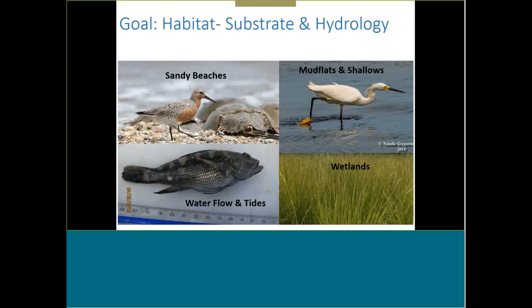And if you're coming at it from a habitat standpoint, looking at wetlands, it's important, as Chris mentioned, to make sure that you're selecting your plants based on what conditions are already there. If you're in a completely saline situation, you're picking Spartina alterniflora. As you did at Sassafras, we did a project at the Blackbird Reserve that was really brackish, so we were picking arum and species that were native there. If you have a really more even freshwater situation, as I have an example coming up on the Delaware River, you're going to be looking at even lilies and other SAV. So it really depends on what conditions are already there, and you're designing for what's appropriate.